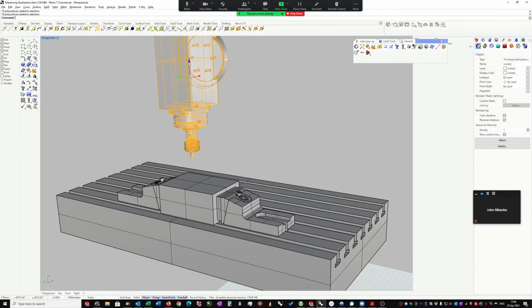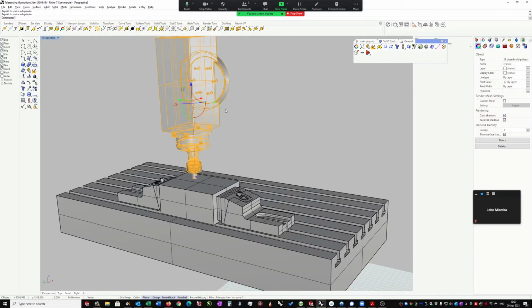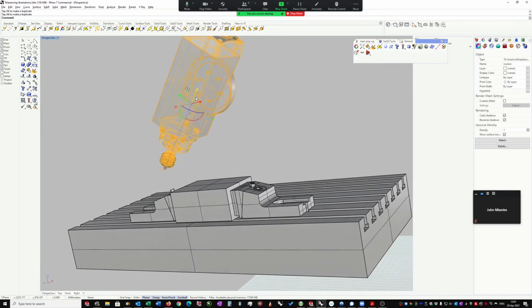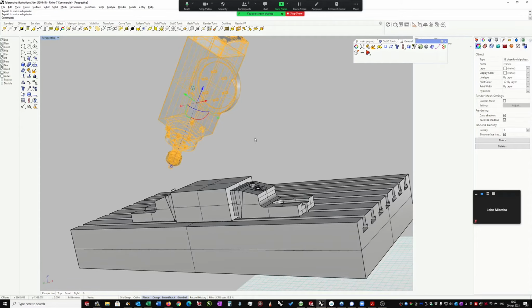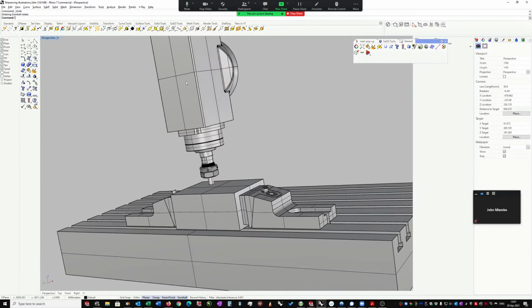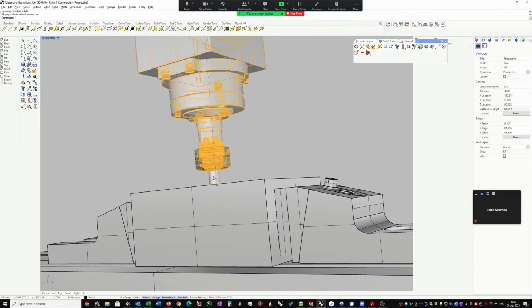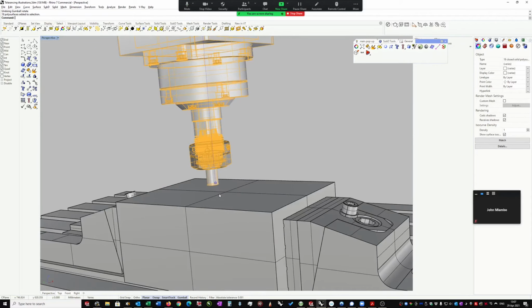Typically the milling machine would be able to come up and down like this, front to back, sorry, and then left to right. And the more sophisticated ones will actually be able to rotate like this and do the same sort of thing, going left to right in those sort of axes. So what you've got to think about is that whoever sets this machine up or operates it needs to understand where they're going to zero their dimension. The zero point is the point at which the cutting head meets this base plane.